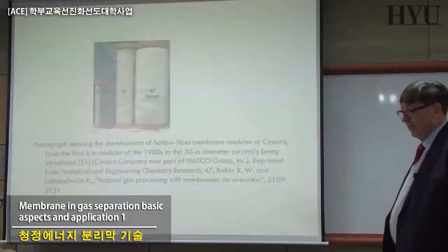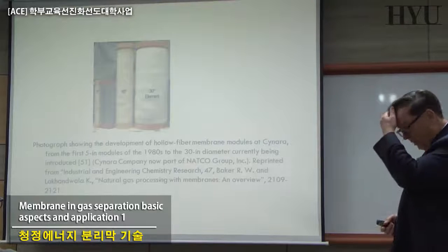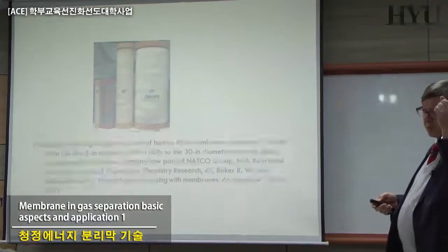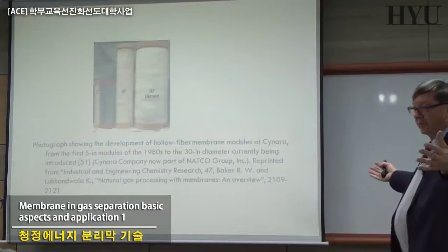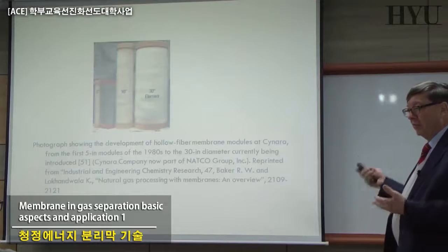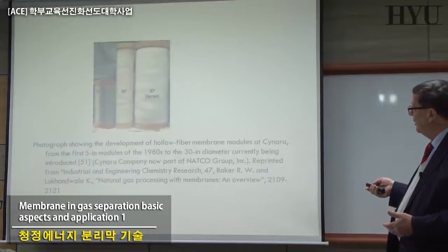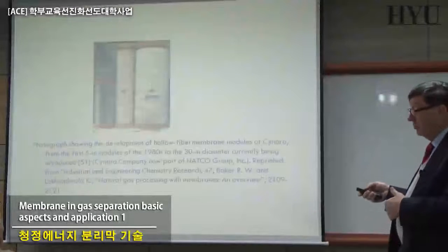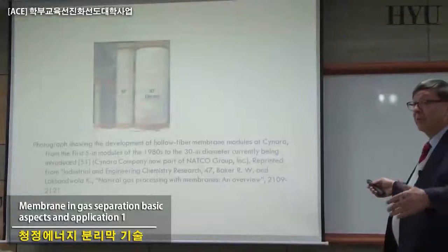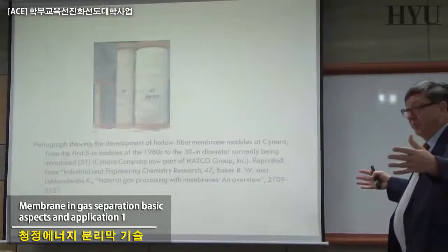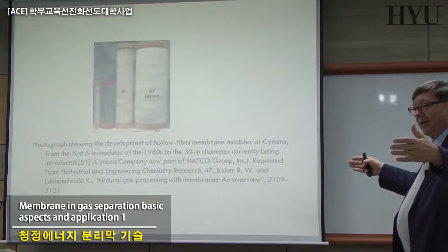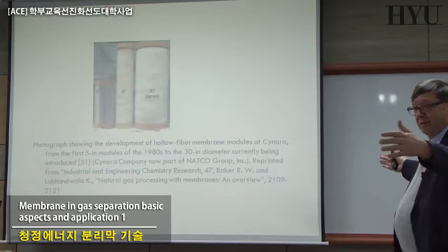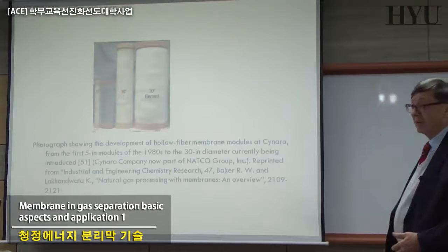Same problem that you have in reverse osmosis. So remember, today one of the ways to reduce the final cost of production of water, or of gas here, is the size of the module. When you are confident about your membranes, there is no reason not to make the module huge. In RO, it already exists. Initially, at my time, modules were 4 inches in diameter and 80 centimeters in length. Today, the modules are 36 inches in diameter and 3 meters high.